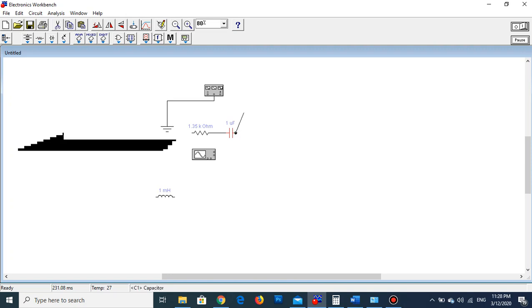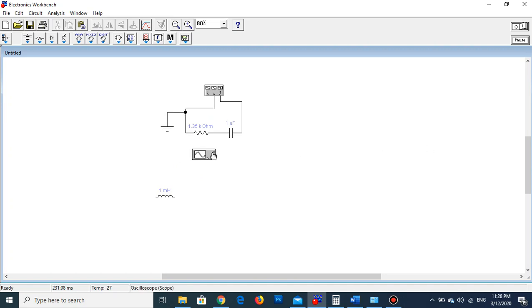It is very simple. The capacitor goes to the positive and the minus to the resistor, like that. And now we should connect the oscilloscope in order to observe both the voltage of the generator and the voltage of the resistor. Why? Because our goal is to compare the voltage of the generator with the current flowing in the circuit, and since the voltage across the resistor is proportional to the current, we measure these two voltages.